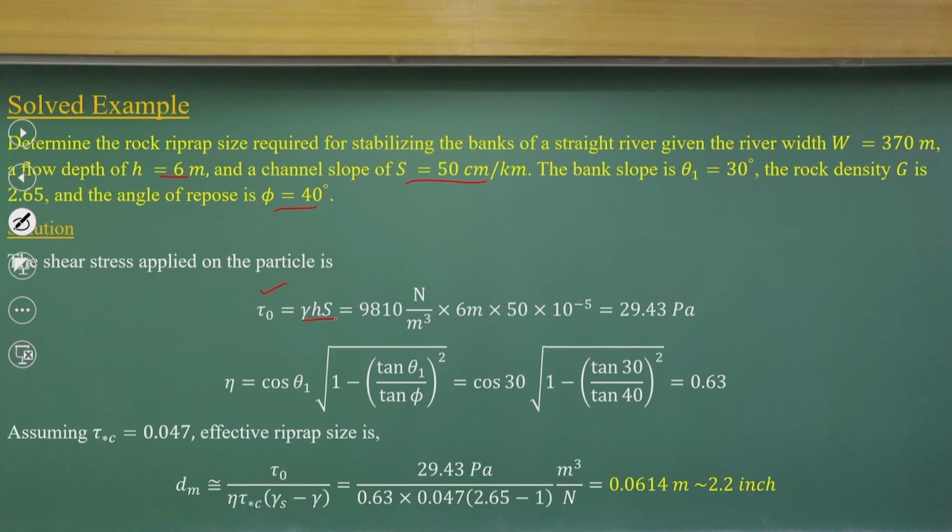We can find that the shear stress acting is close to 30 pascals. You can also compute the component, and finally, you can assume the critical shear stress value, which we discussed earlier, as 0.047, and substitute this value, then you can compute it.